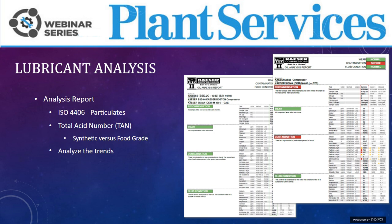Here are two sample reports. The one on the left shows an oil sample that's passed inspection, whereas the sample on the right shows that the oil is operating in a severe condition in regard to particulate contamination. The particulate count's high, along with the oil cleanliness not being sufficient. So having this trend analysis helps to determine the condition of your equipment, and if the situation is a known problem, helps you figure out how to address those issues as you move into the future.